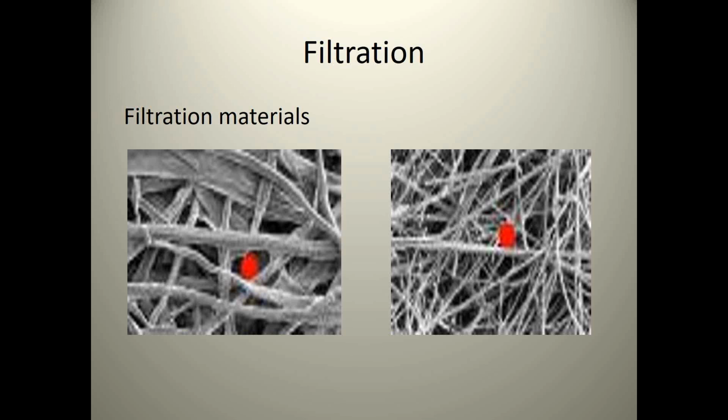Now, when you're talking about filter materials, a lot of times vendors come in and they say, oh, I've got these filters and they might be 10 micron beta 1000. The very first question you'll want to ask them is, what is the filter media made out of? If they say paper or they say cellulose, there is no way to get beta 1000 with paper or cellulose. Not even really many of the cloth ones can get those kind of beta rated numbers.